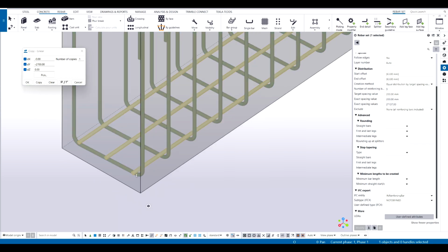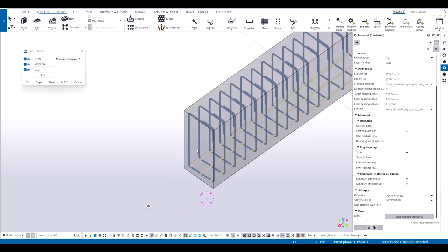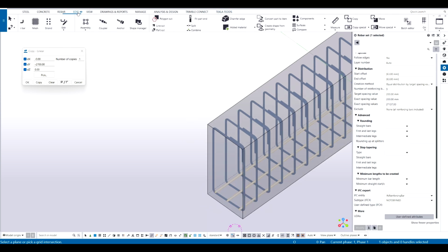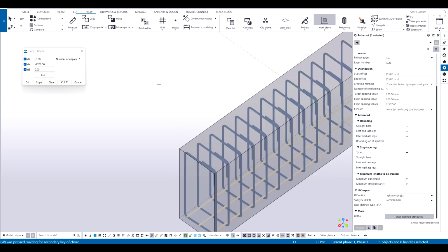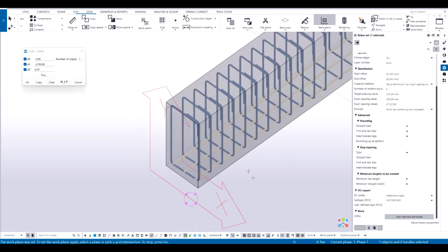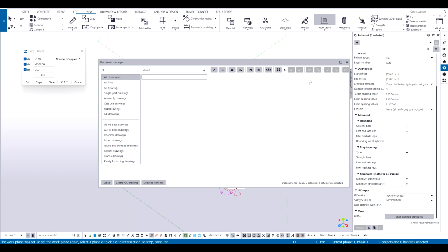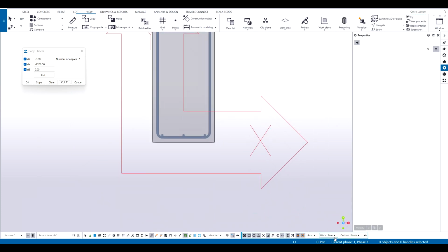Now, I don't know if this is quite a useful trick. Where's this edit work plane tool? Where do you get that again? Yeah, so work plane tool, I have set it as WT on my keyboard, and I make this the work plane. Now when you make this the work plane and then hit Control P, it becomes like this. This little toggle is very handy.